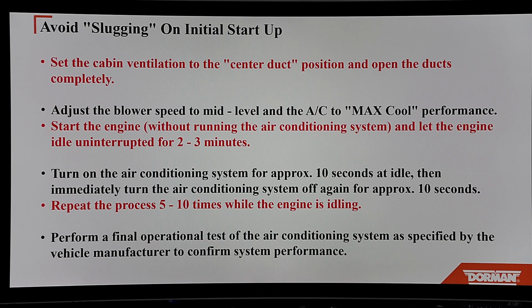Start the engine without running the AC system and let the engine idle uninterrupted for 2 to 3 minutes. Turn the AC system on for approximately 10 seconds at idle and immediately turn the air conditioner off again for 10 seconds. Repeat this 5 to 10 times. Perform a final operation of the air conditioning system as specified by the manufacturer.